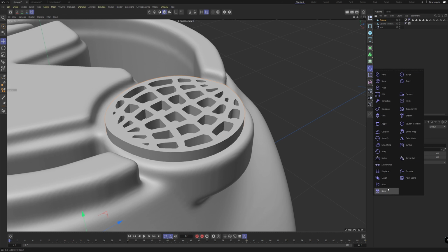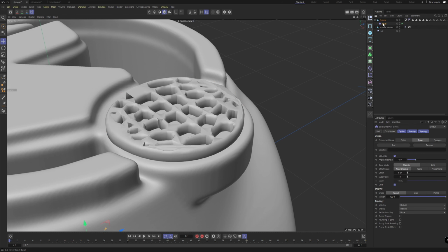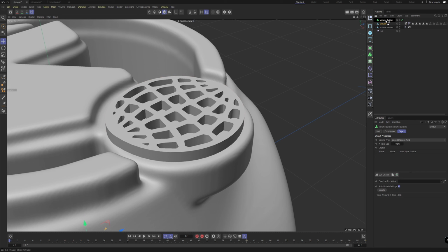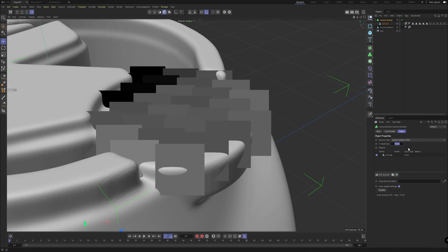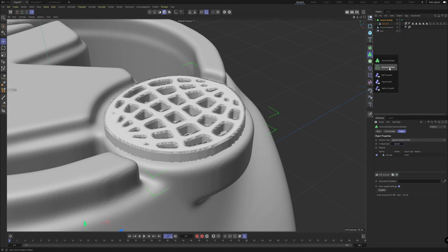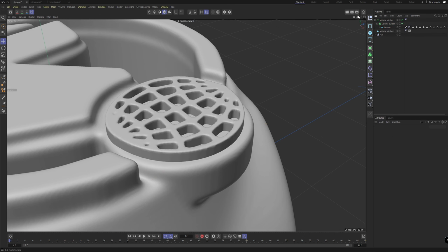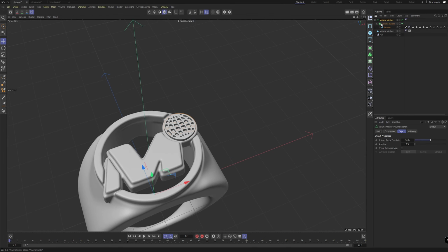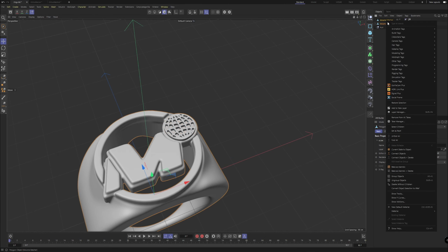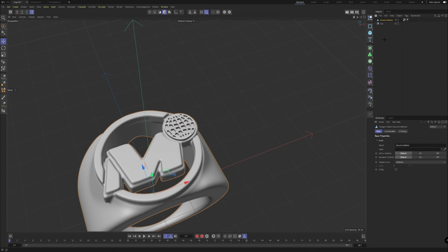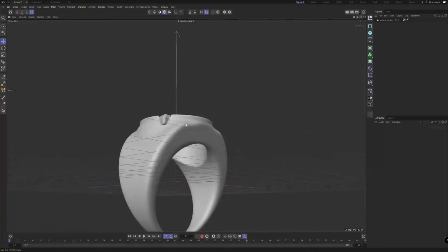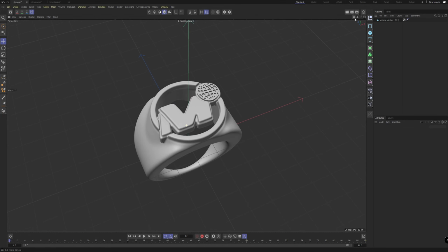See what a bevel does for us. It may well cause issues. Yeah, it always seems to cause issues. So if in doubt, we can just whack in another volume builder. Make it 0.5 volume measure, unsmoothing it, but just leave it something like that. It's a little more rounded than it was before. And just like that, we can hit C. We can probably just combine these, connect objects and delete, and we have our volume built ring. So now, for the exciting bit, we've done the modeling for all intents and purposes.